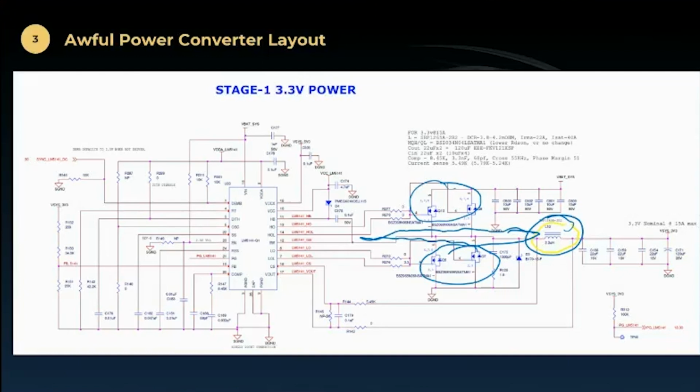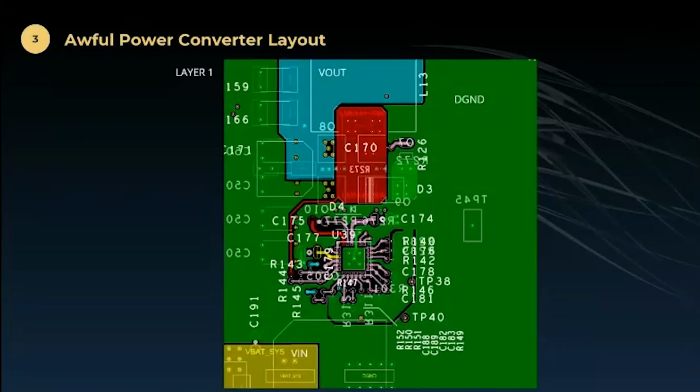So we need to find it and keep it small. I'll typically color all the nets on the board one particular color, and then I'll go look for that switching node and make that a different color. Here we've done it and colored it red. That's the switching node for that circuit on this particular board. I also colored the V out blue and the V in yellow.